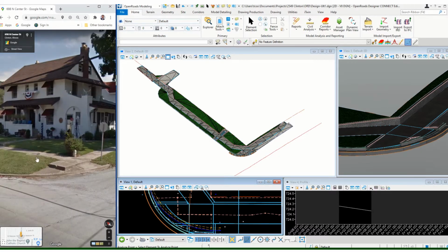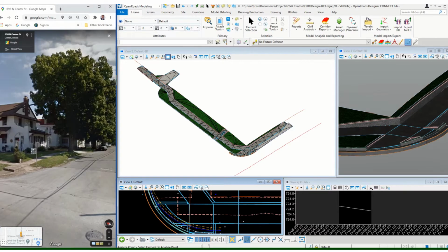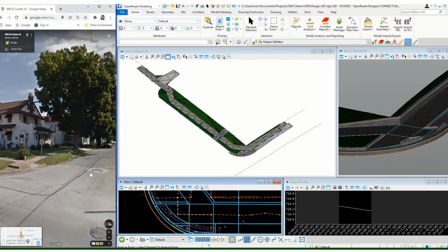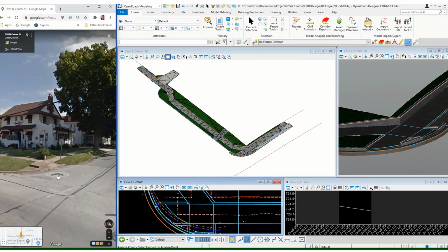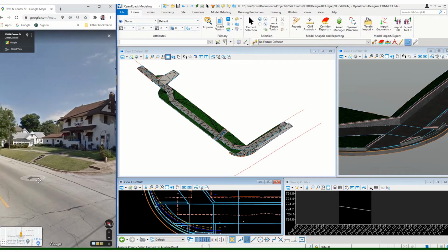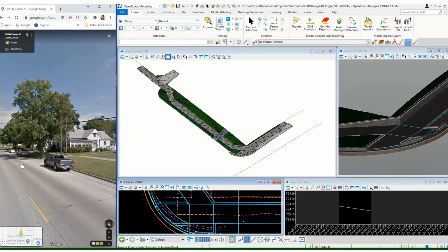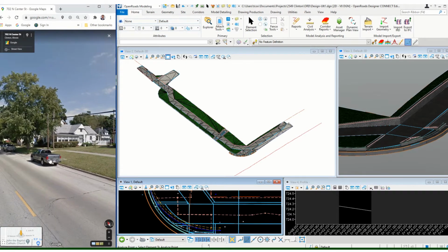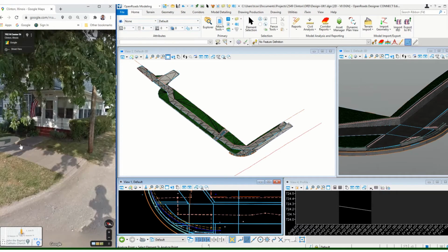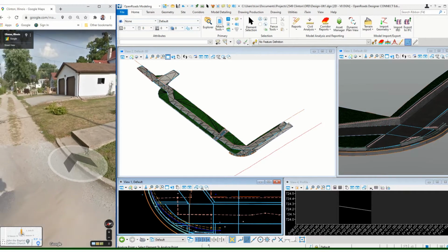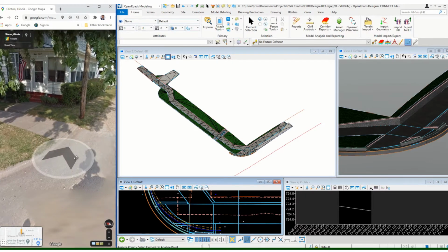So here's the situation. At the back of the sidewalk, of course, is the existing right-of-way. You can see that the sidewalk's up high. Also, the side road has a grade of about 6%. So there's a challenge. Center Street's profile is going downhill some. You saw the stairs back there. We also need to get this alleyway taken care of. Again, very steep slope, and